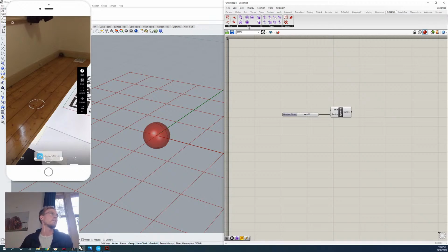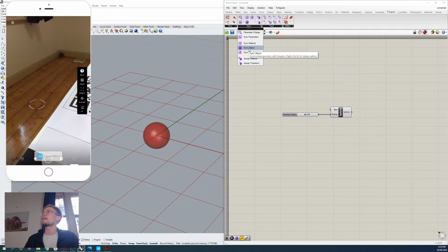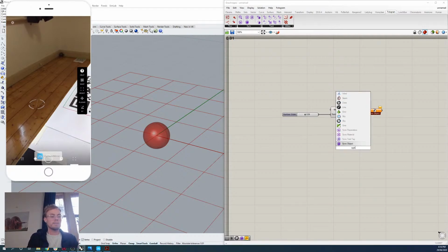As I mentioned before, in some of the upcoming workshop sessions, we're going to look more in depth at pretty much all of these different tools. So I'm going to click on sync, and we're going to first look at the sync object component, which is right here. I just want everyone to click on sync object and click once on the canvas to drop it there. You could of course double click and type sync object and choose it again. It's that cube with the arrows pointing around the side of it. So just go ahead and drop that onto the canvas.